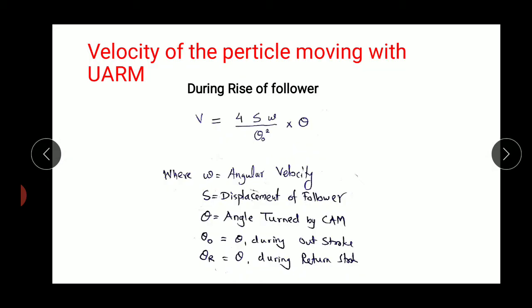Now the next part is the velocity of the particle moving with uniform acceleration and retardation motion. So the velocity of the particle, while it moves with uniform acceleration and retardation motion, whether it is a particle or the follower, is represented by V equal to 4 S omega upon theta O square into theta, where V is the velocity of the follower, S is the displacement of the follower, that is the maximum displacement of the follower, omega is the angular velocity of the cam, theta O is the angle turned by the cam during out stroke, this is constant, and theta is a variable angle turned.